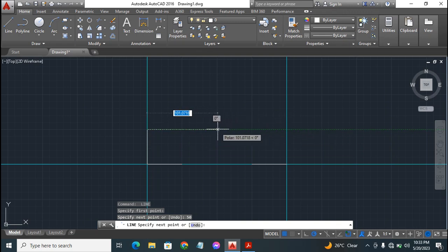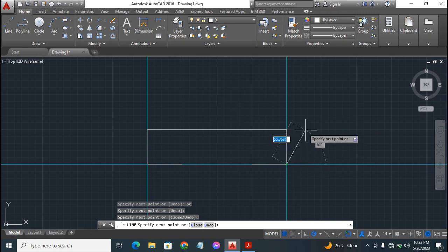As you can see, where my cursor is right now, you see a dotted line right across the horizontal. That is what we call an extension line. Okay, it helps us to easily locate points. Alright, so I will lock this cursor to this point of intersection, click on it, then I'll join back to this end. Now we've gotten that.